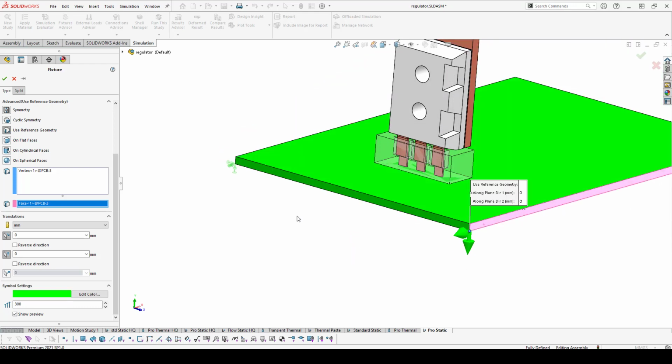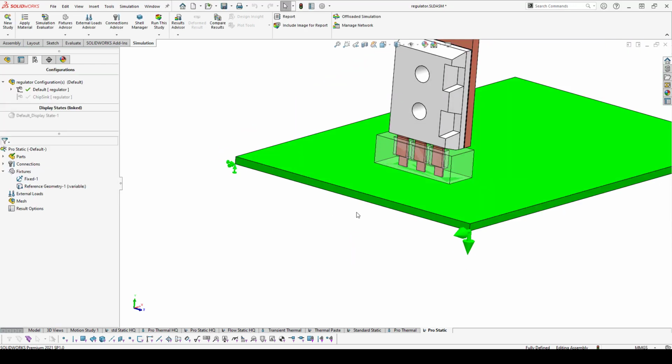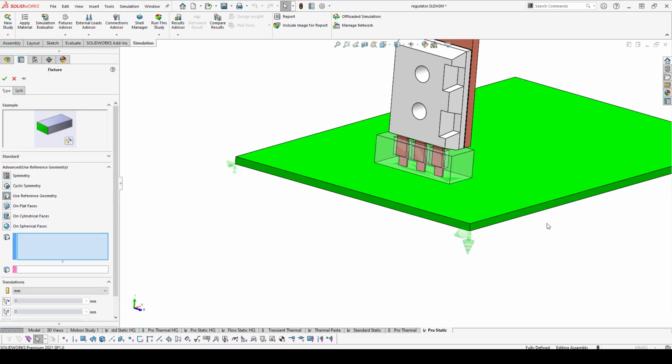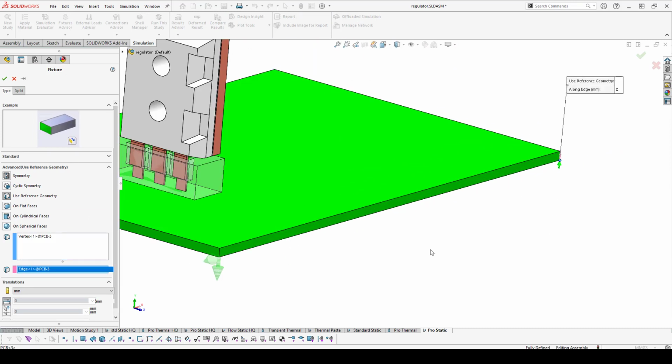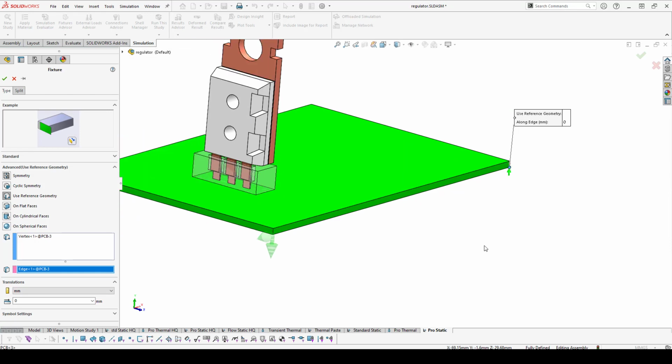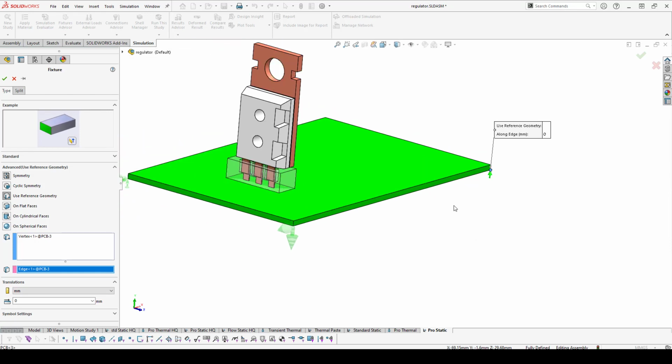But now this isn't enough. It helps hold it in place a little better, so now it's not free to rotate about that ball joint. But picture there's an imaginary axis that connects this point to that one. This board is able to rotate around that imaginary axis. So we're going to add just one more fixture over here, somewhere off of that axis, and we're going to restrain this in the direction depicted by this little green arrow there. So now you can see I'm restricting it from being able to freely rotate.